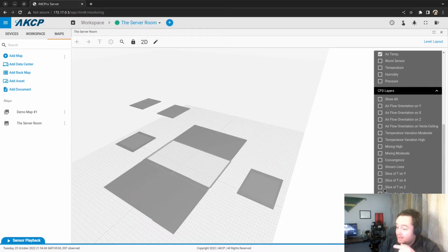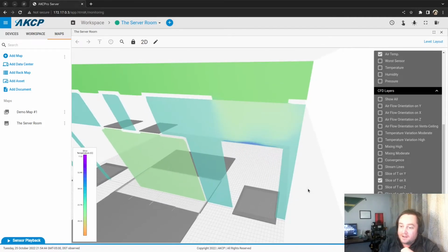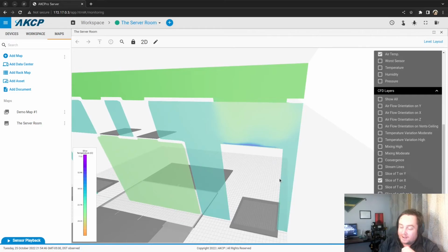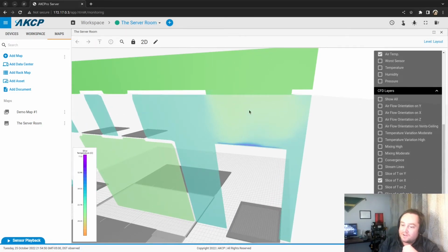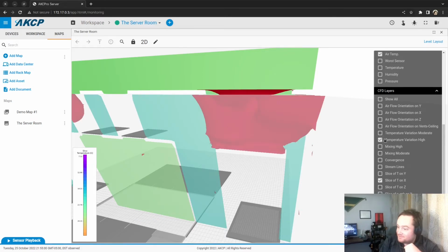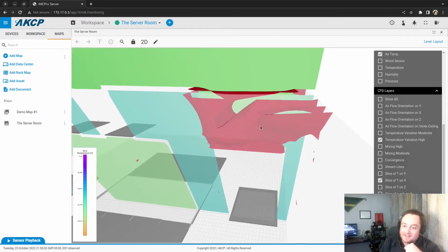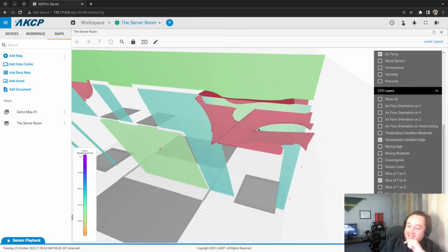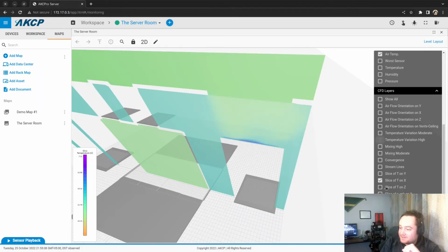I think my mistake is a really nice example right there with my boundary condition that is not good, because the air is way cooler than supposed to be when it enters the crack, so my model fails. Like I told you, we can see that I made a mistake. That's really good, because we can see how to detect it.